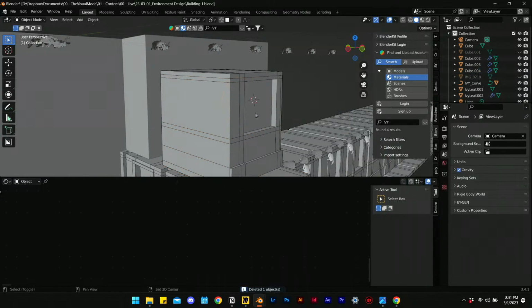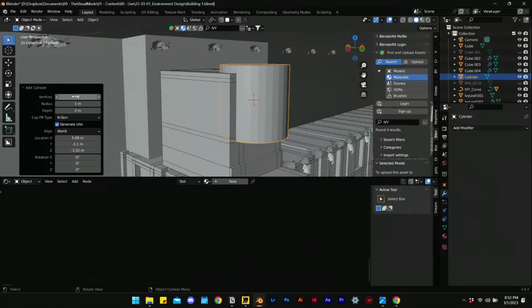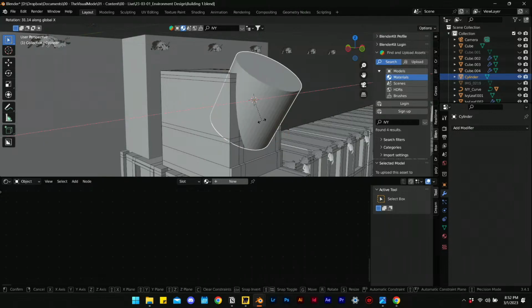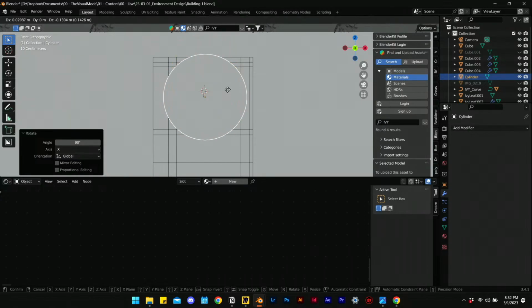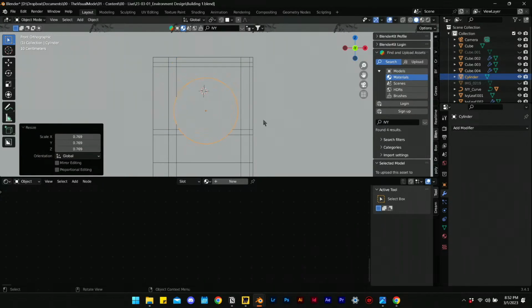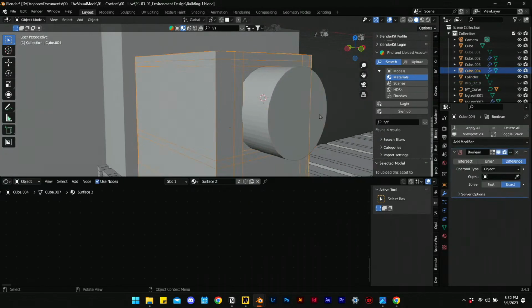What I should have done is, when you create a cylinder, you want to just go over here to the settings and add more vertices. So we can see with fewer vertices, it even becomes a cube again, or a triangle, or an octagon, whatever you want. And if we add faces, I'll add not too many. I don't want to bloat up the scene, but you can add 60 faces all around. Now we rotate that. I have to reposition. So I'm going to have it fit as it did before between these two lines at the top, a perfect circle. Select right here.